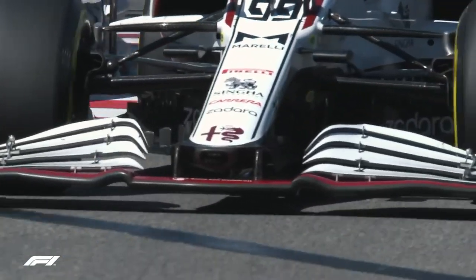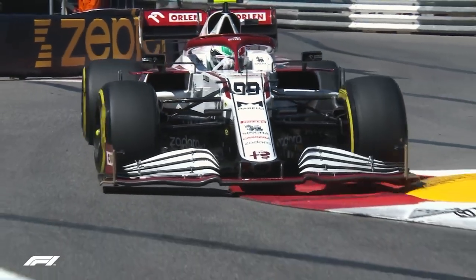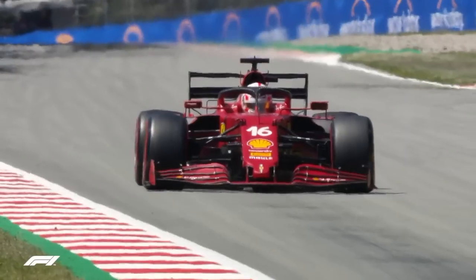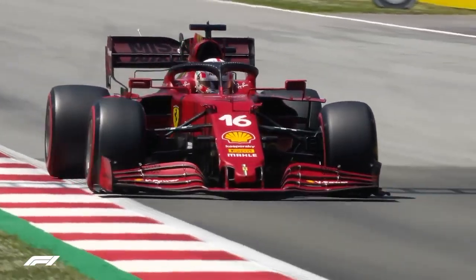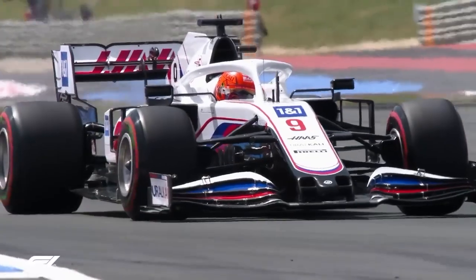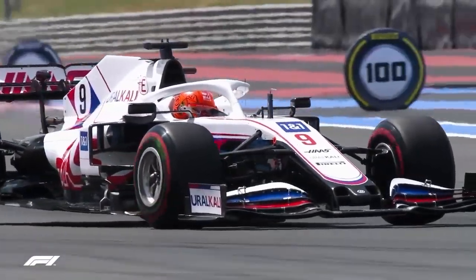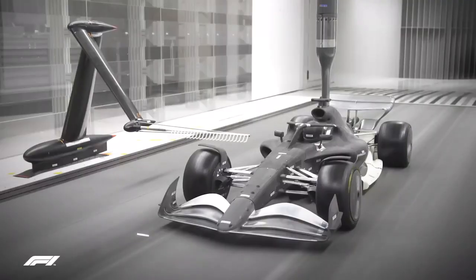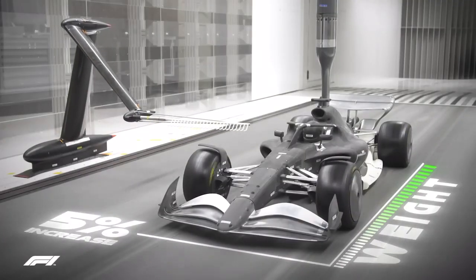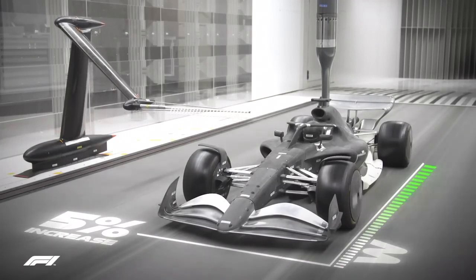Lift, conversely, poses a significant threat to downforce. It is the upward force that could potentially lift the car off the track. This is where the angle of attack is introduced. Angle of attack refers to the angle at which the incoming fluid, air, is hitting the object in motion, often a wing of an airplane, or in this case, the front wing of an F1 car. It directly impacts the lift production of the object when it is moving through this fluid.